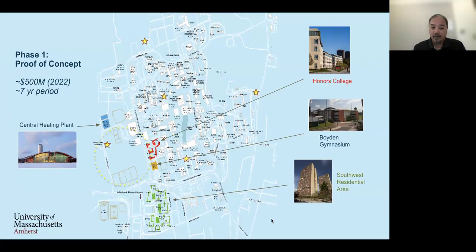But before we went down all these other avenues, first we wanted to play out our ability to implement Geo-Exchange technology throughout campus. So as the final parts of this phase 1 effort, we installed 4 other test wells. You can see in the 5 yellow stars there which ones we did and where they were on campus. And we analyzed the thermal properties at each location, so it would help inform our current and our future planning discussions if we were to look at converting a building or a series of buildings into ground source heating and cooling systems.